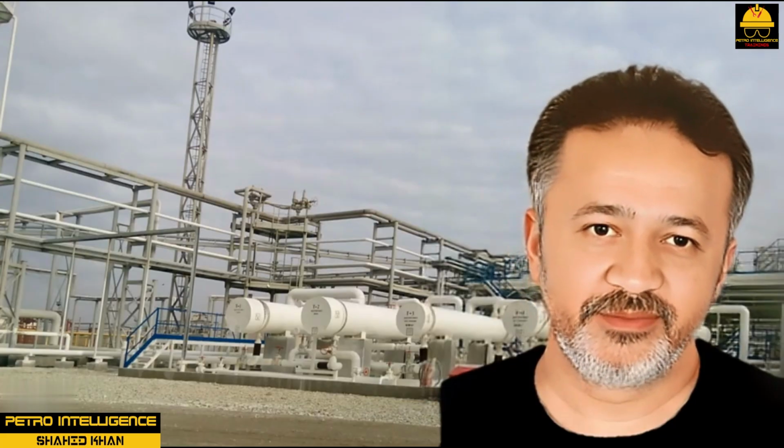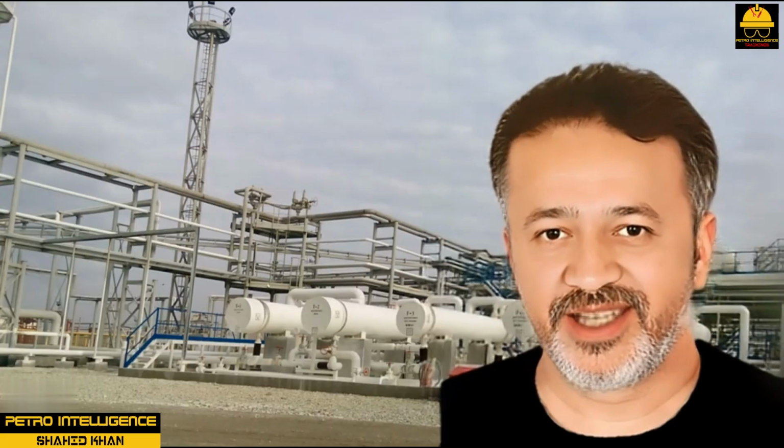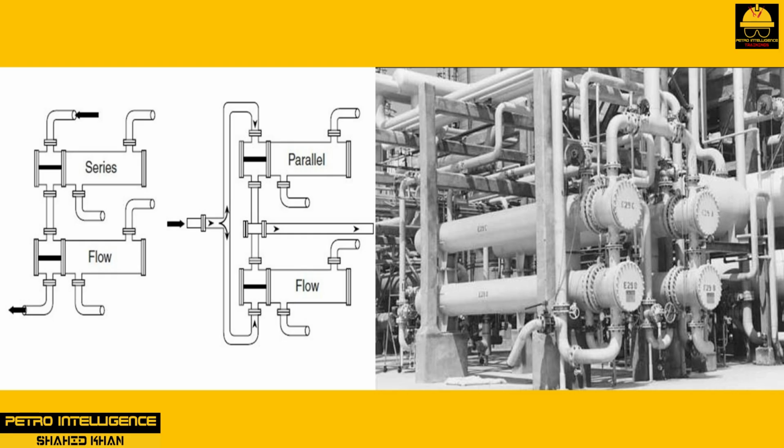Parallel and series flow. Heat exchangers can be connected in a variety of ways. The two most common are series and parallel, as shown in the picture. In series flow, as shown in the picture, the tube-side flow in a multi-pass heat exchanger is discharged into the tube-side flow of the second exchanger. This discharge route could be switched to shell-side or tube-side depending on how the exchanger is in service. The guiding principle is that the flow passes through one exchanger before it goes to another. In parallel flow, the process flow goes through multiple exchangers at the same time.